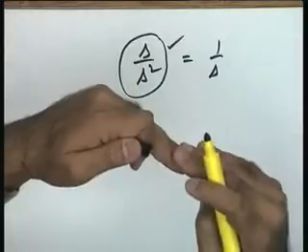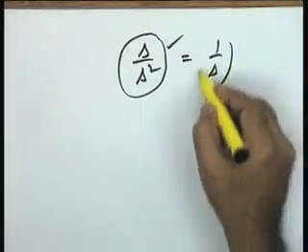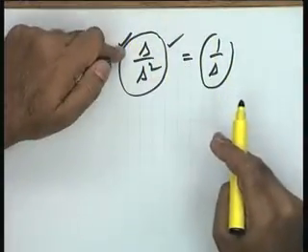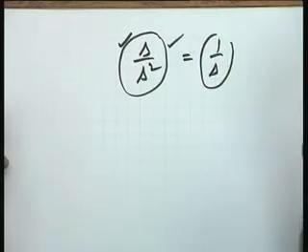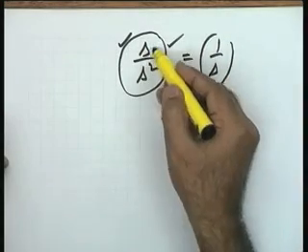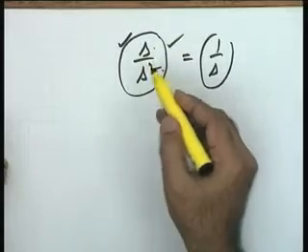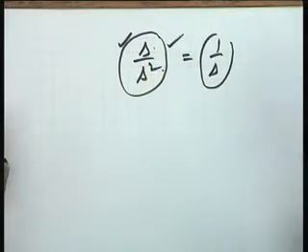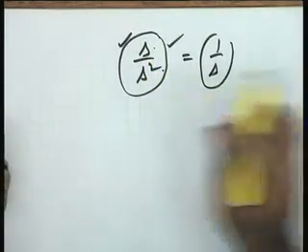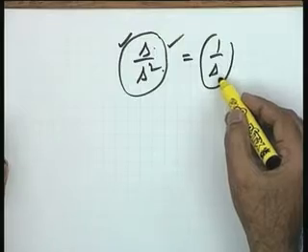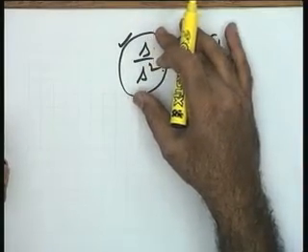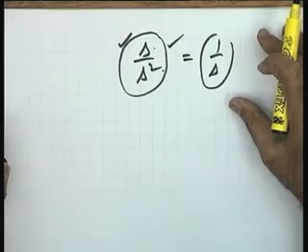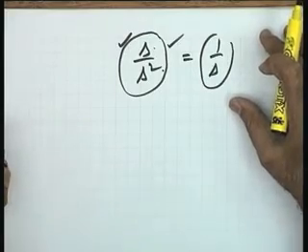Now, if you say practical questions, it means practically this system with this particular transfer function will approximate an integrator, it will not be an exact integrator. After all, when you say s by s squared, it means this 0 is at least close to the pole at the origin. So, the real system is not 1 by s, which would be a perfect integrator. This system will approximate an integrator because of imperfect pole 0 cancellation.